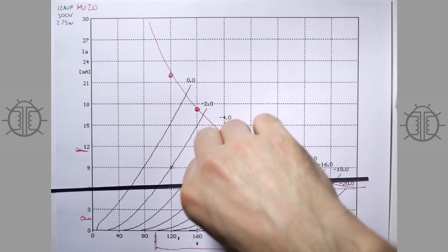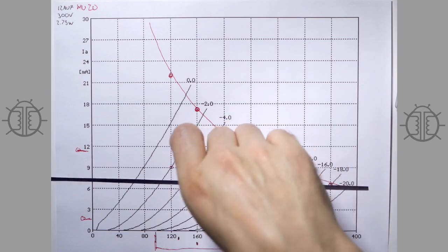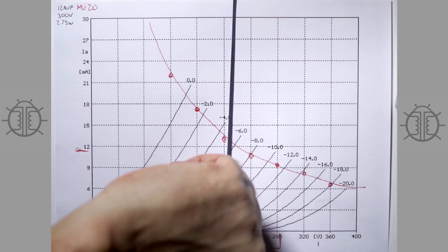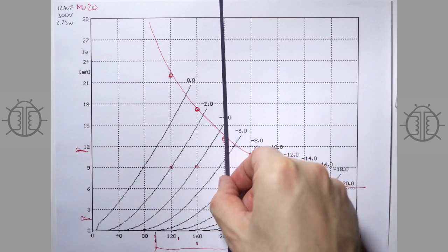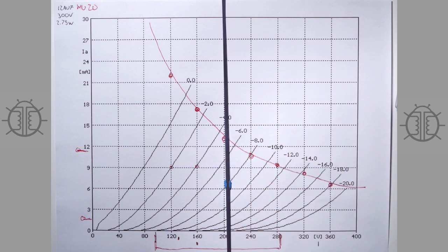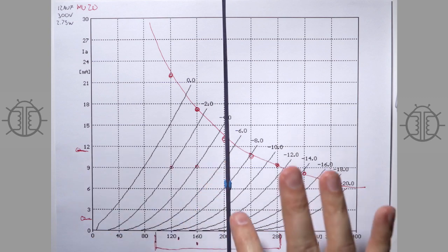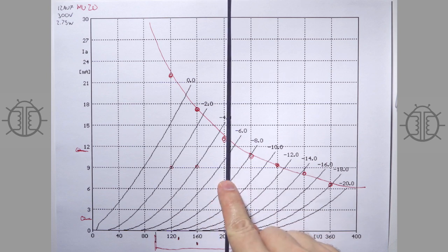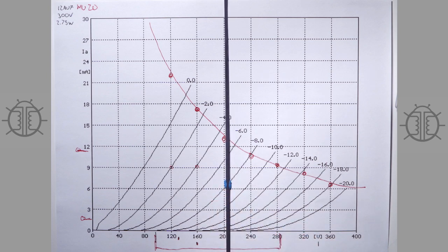So that's fun. So the opposite of that, or it's the same in a different way, is the transconductance. So the transconductance of a tube is if the line is right up and down like this, and you can see how much current you gain. This depends on your operating point, obviously, but how much current you gain for input voltage. So transconductance is current out divided by voltage in.